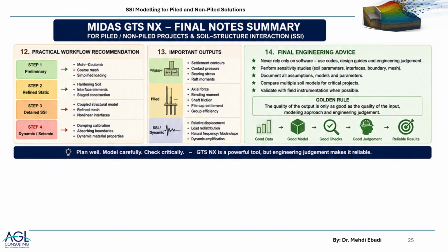Sometimes you find that by changing some parameters, mainly in more advanced models, not models like Mohr-Coulomb, starting from hardening soil model or Cam-Clay or those levels of models, if you change one parameter slightly, that will have big impacts on your results. So that sensitivity analysis will help you at least in that aspect.